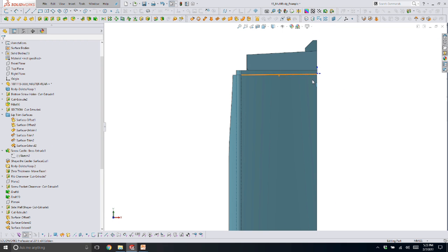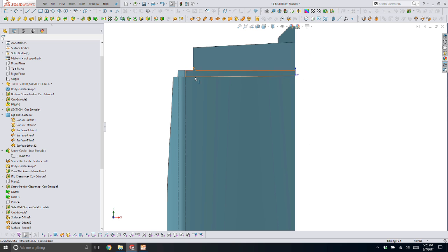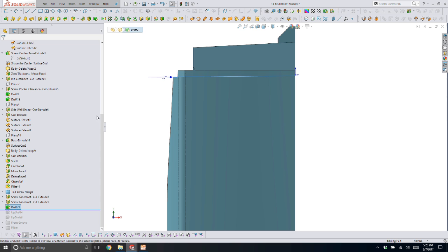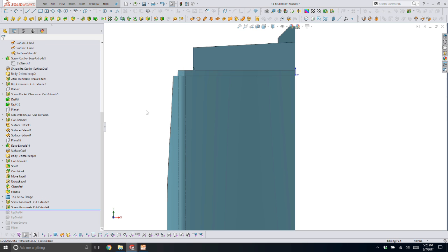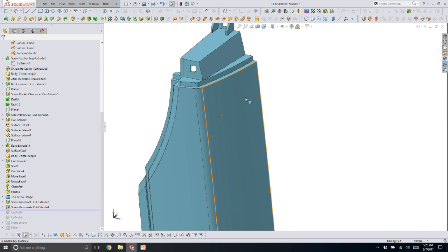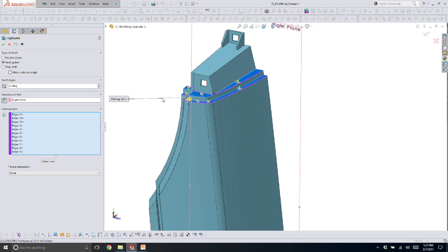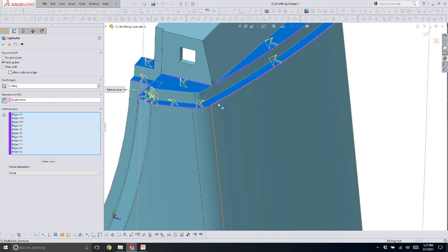So now when the other part comes in here, unless we angle the bottom face of the other part, it's not going to line up, right? Because this face is now at a 0.5 degree. So to work around that, when cosmetic edges need to be straight for design intent or industrial design intent purposes, what we can do is use parting line draft and draft from the edge that you want to be visually straight, and you need to pick the entire chain of edges.